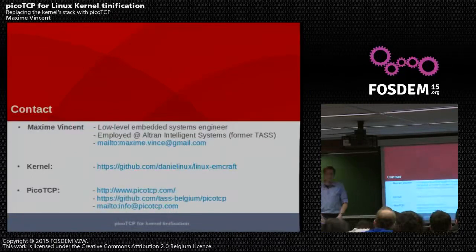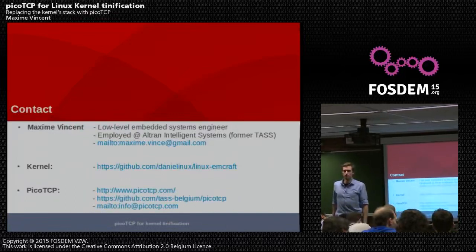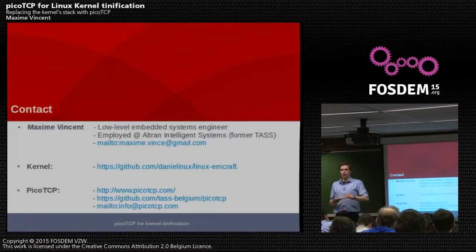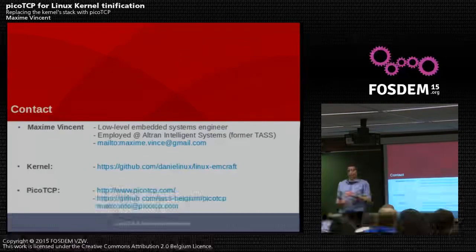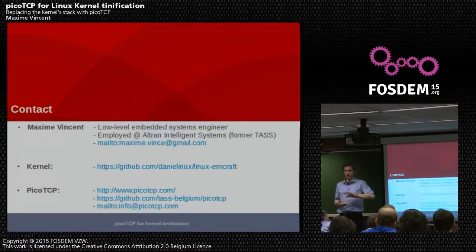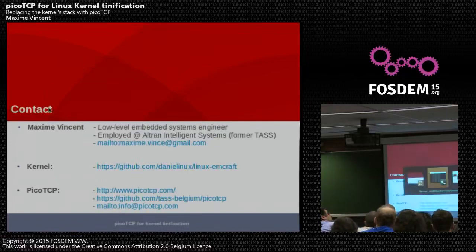If I just need a Linux box that is sending me packets, like temperature, just pushing a value once in a while, how low can I compile it? Because you said it's 43 kilobytes, but that's with TCP/IP. If I just need UDP, how small can it be? Well, I haven't tried only UDP in the Linux kernel, but PicoTCP with just UDP support should go somewhere near 20 kilobytes. I can maybe show you a compilation of PicoTCP right here.